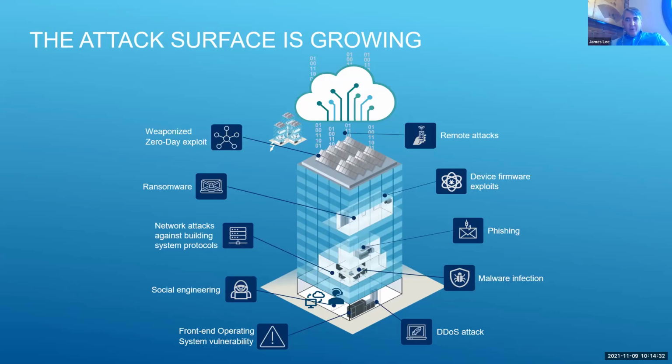As the industry has moved from proprietary or industry-specific technologies like BACnet MS/TP, which is a twisted pair network, to IP-centric controllers, which is by far the direction of the industry, we're opening up more and more attack points, not only into the critical infrastructure that we have, but also as attack vectors into the enterprise as a whole.